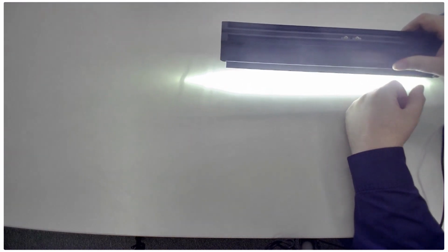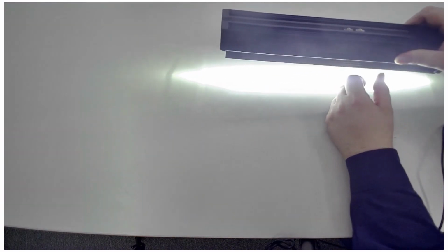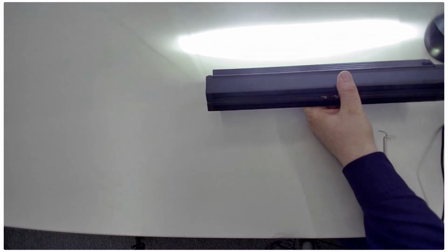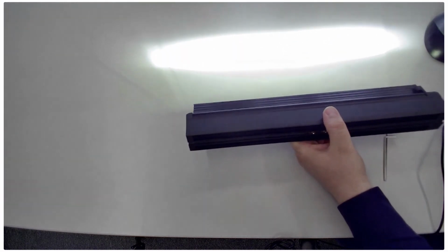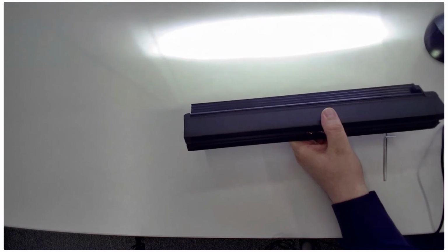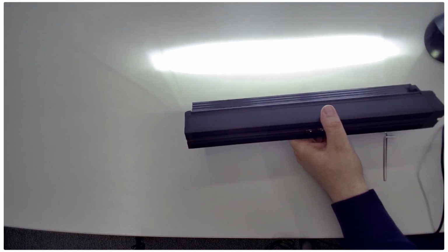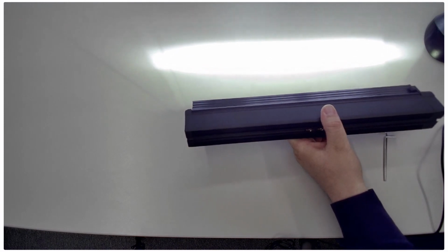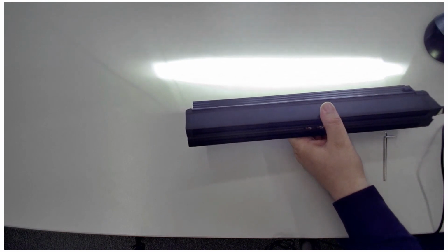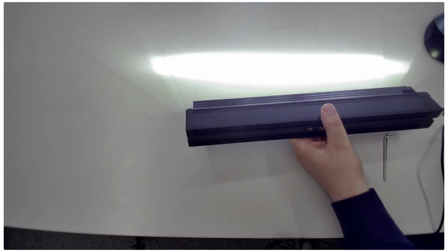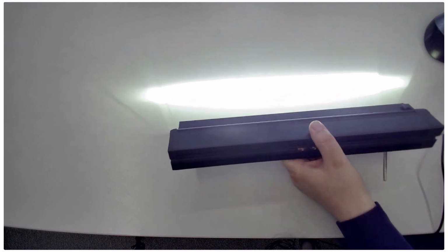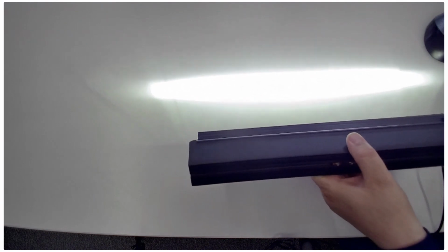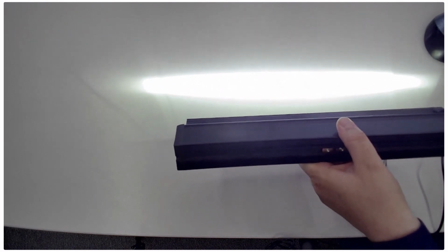So we don't need the whole surface to be illuminated, but we need way more intensity on the level of the object, because line scans have higher line frequencies and shorter exposure times. So this forces us to use as bright lights as possible. Also, this brightness is achieved by refocusing LEDs. So this is what happens here.